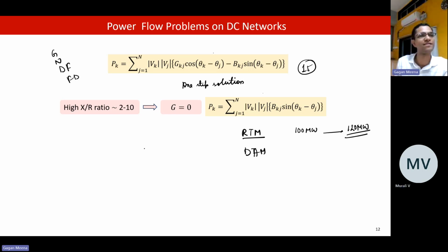Right now in markets, power exchanges, DC power flow equations are used. This is one application. Another application where DC power flow is used is in planning problems. Let's say I want to plan for the next 30 years. The Central Electricity Authority plans for the next 30 years. Even for the next 10 years, they have given this 2030 transmission expansion plan, that we need to erect these new transmission lines, storage has to be procured, and all these things.